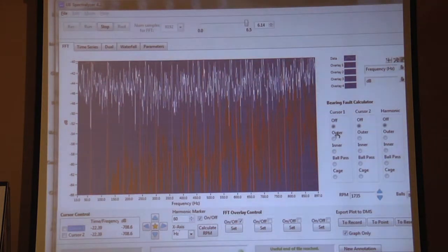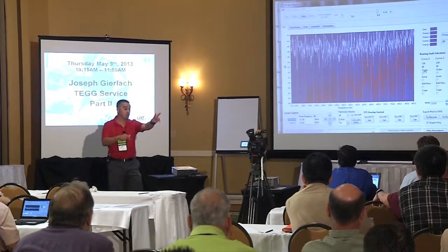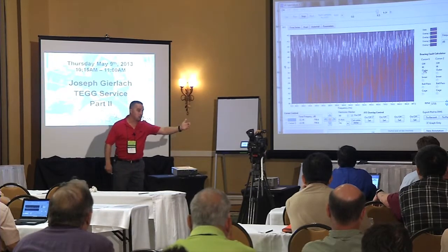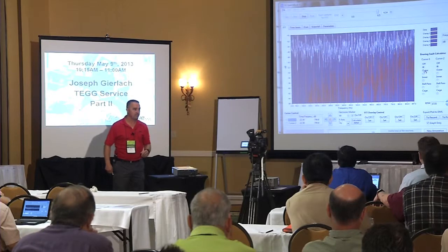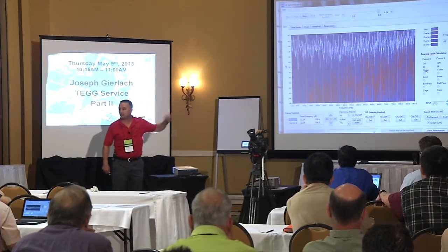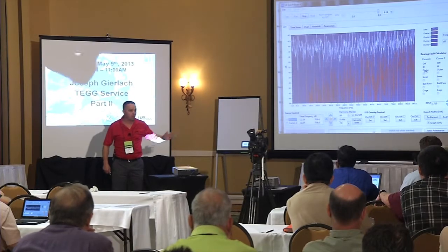Okay, so in this example here, if we look, both recordings have some 60 hertz where they're hitting in both the arcing and the tracking, right? And both recordings have a very large abundance of frequency noise in between each harmonic marker. Those are the two similarities. So I can communicate to a customer, it is in fact an electrical fault. Does that make sense? But to just look at this tool, there's no way to tell which one is which, agreed? We just know we have electrical faults.